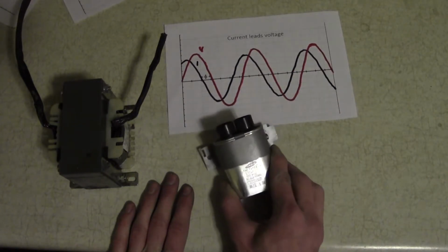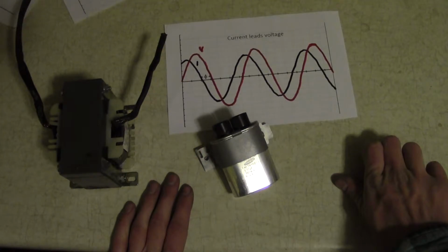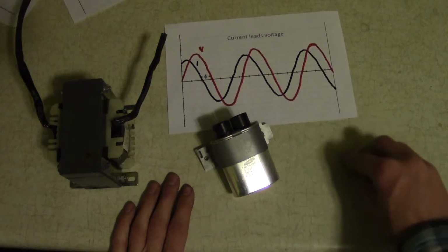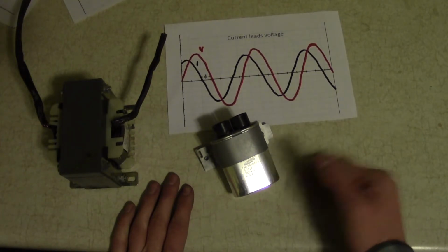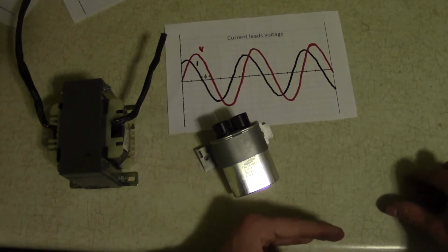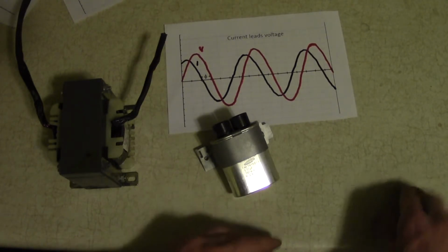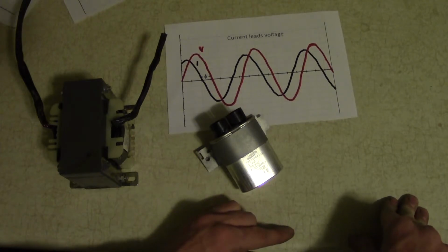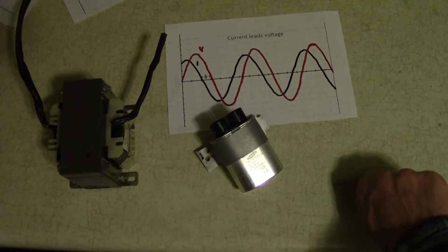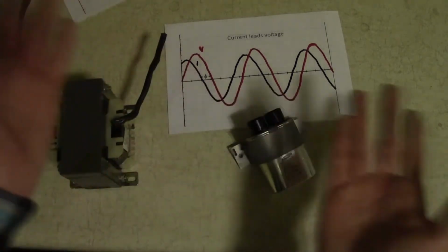My other option would be to have a rotary toggle switch, and basically you have 0 and then you chunk and you hook it up to a small capacitor, chunk, a medium, chunk, larger. So the potentiometer would be infinitely variable, completely linear, whereas the toggle switch would just be set values. So maybe the power factor would increase by 0.01 each time. If, for example, my power factor was reading 0.85, chunk, 0.86, chunk, 0.87, chunk, 0.88, I just keep going until I have enough capacitors hooked up in parallel that I'm able to match my inductance and get close to 1.